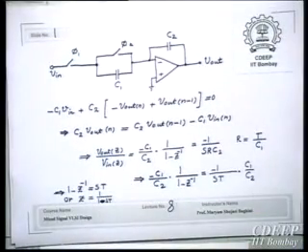Okay, so coming back to this, how to make the backward Euler approximation? This is backward Euler approximation. Okay, so this circuit is very interesting. Now, see, how to avoid delay. What was the point with forward Euler? Forward Euler creates a delay. Now we want to remove this delay. What does it mean? In forward Euler, we would charge the capacitor and then discharge it, right? Now what we do? We charge and discharge it at the output capacitor simultaneously. And then we reset it to 0 in a separate phase.